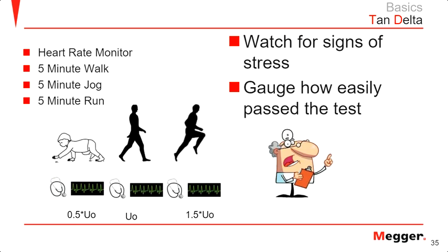So if you are doing a PD test, right? And that's an excellent question, by the way. A lot of people have the same question. When you are doing a VLF, just a VLF, purely pass or fail test, you can hook up all three phases at the same time and run it along. But when it fails, how would you know which cable failed? So it's a kind of pass or fail that you are willing to test, right?